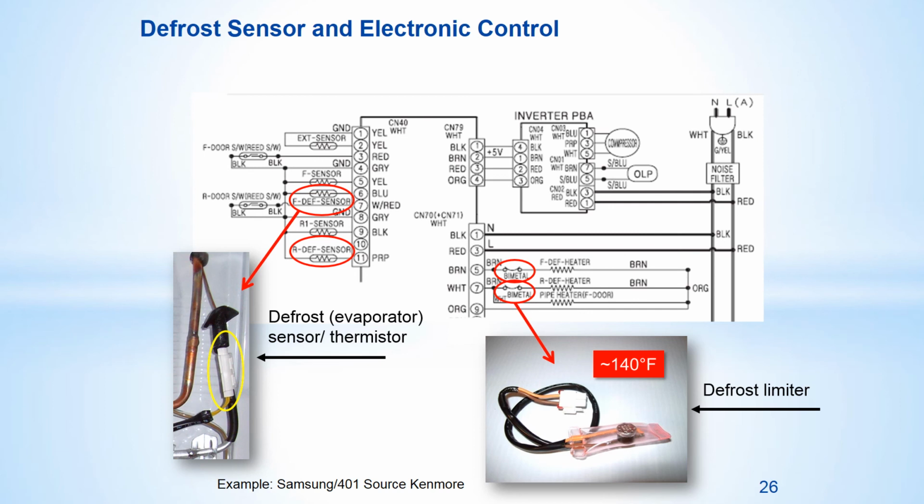Most electronic models have forced mode to check the function of each of the components, including the defrost system. Follow the directions included in the tech sheet for the specific model. Please note that before initiating a component operation mode, it is recommended that any error or fault codes be retrieved first, as sometimes the forced mode will clear any error codes.